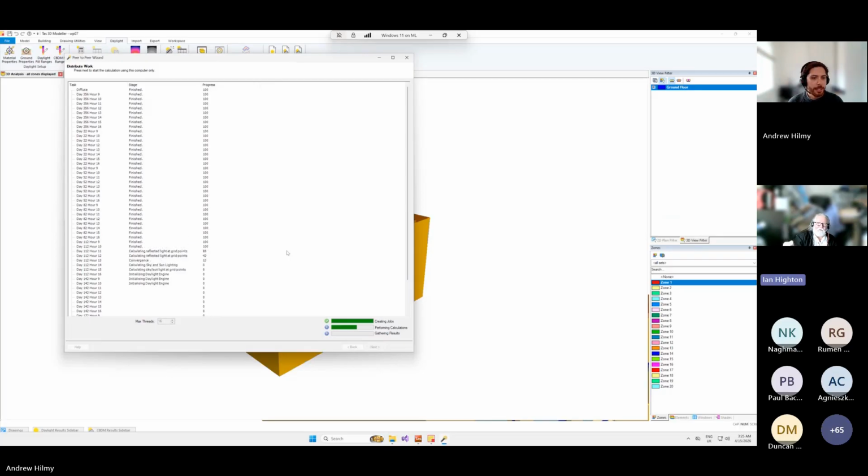And then I can't remember how many now, but I think we do 7 days through the year in the center of each month for the direct stuff, and then each hour through the year you're doing that balance based on the weather data of how much direct is there compared to how much diffuse, and then you just superimpose those two solutions on top of each other to get the complete daylight map through the entire space for each hour through the year effectively.